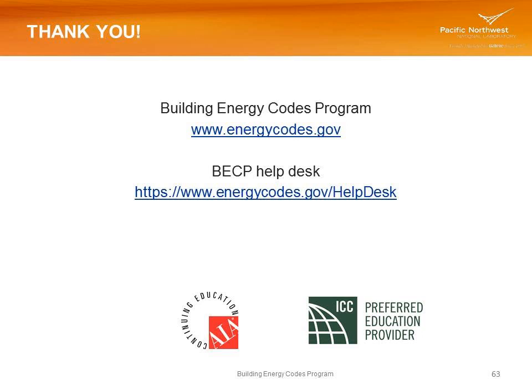Once you get into multiple zones, well, actually, they do have ones that will go either heating or cooling, but not both at the same time. But you usually need a heat source in the building, and so usually they are heat pump systems. They could install a system that just provided cooling and then have an electric resistance heater in the indoor cabinet, but that's pretty rare.